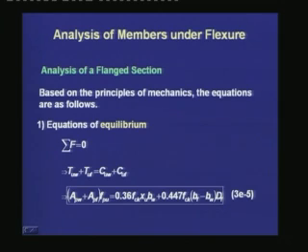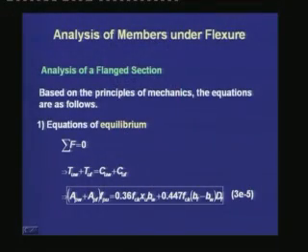And the TUW and TUF are expressed in terms of the area of the prestressing steel and the stress, which thus gives that Tu is equal to APW plus APF both times FPU, and that is equal to the CUW, which is 0.36 FCK XU BW, plus CUF, which is 0.447 FCK times BF minus BW times DF. Thus, this equation is the first equilibrium equation.